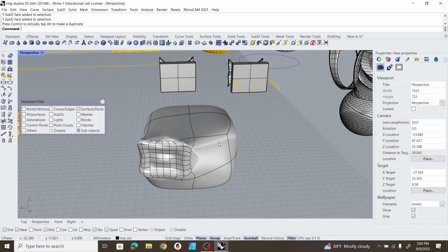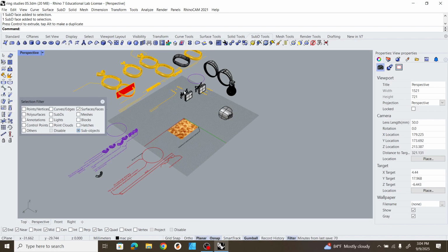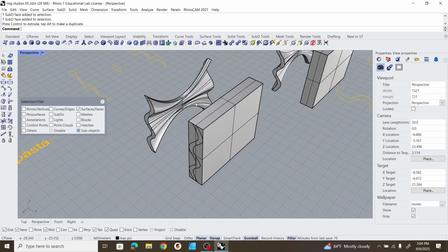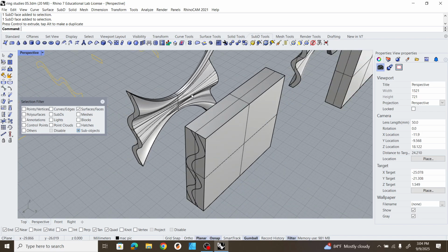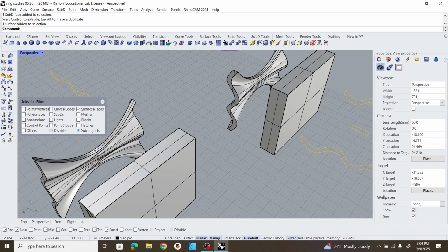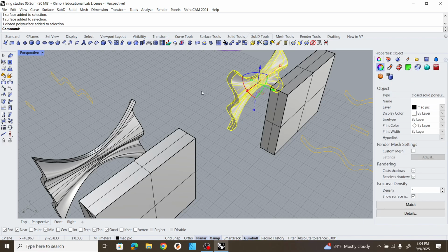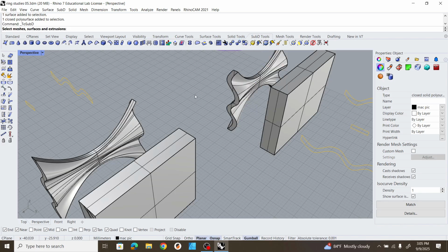So you have this whole suite of tools that you can use. I might be wrong about this, but you should be able to take your objects and translate them to sub D, because it does have a convert objects to NURBS, convert to sub D. NURBS are what we're using in Rhino as the base of it.